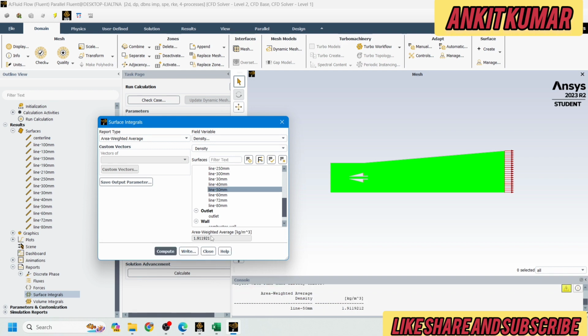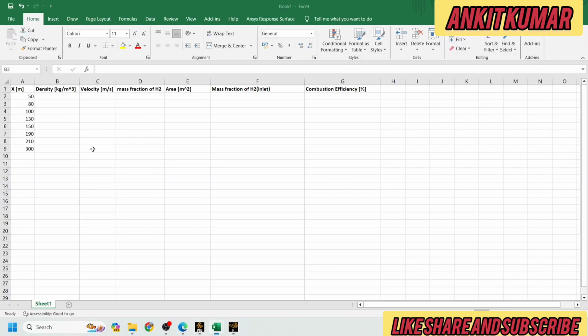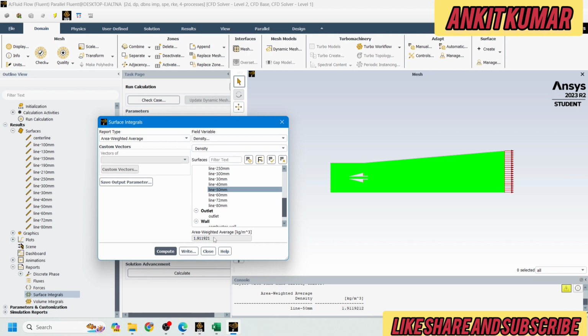It will give the area weighted average density value in kg per meter cube, which is the unit of density. It is giving the average density value with respect to area at 50 mm. So I will note down this value in my Excel sheet. Either I can select and copy from here and paste it, or in this box also we can see the value. From this box also I can select, Control C, and then paste it in the Excel sheet.